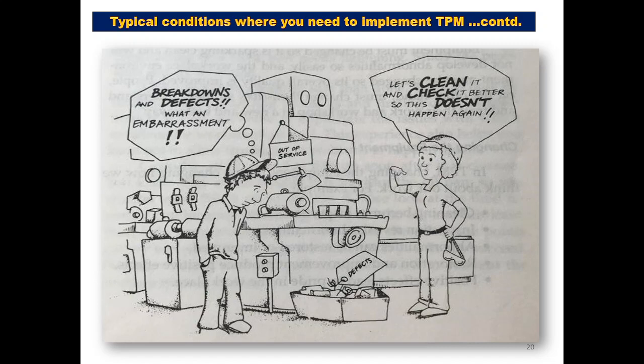Using eyes, he can identify dust spillage, leakages, unsafe parts in the machine. Using his nose, he can smell the abnormal odor like burning of electric motors or electrical accessories. Using his ears, he can hear the abnormal rattling or knocking sound from the broken inner parts or bearings in the equipment. Thus, cleaning is inspection, and inspecting for abnormality using one's senses.